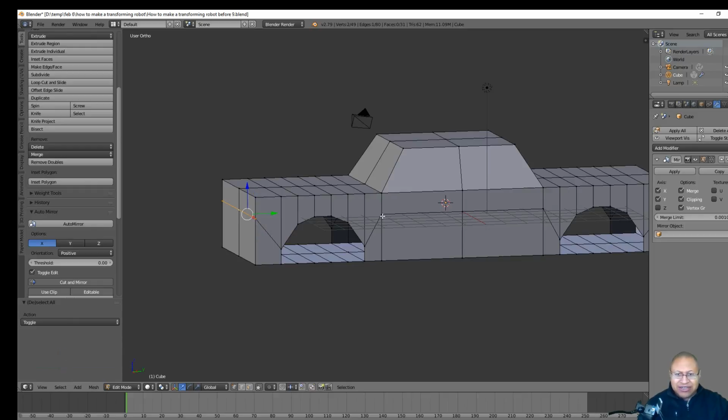We're also going to click here as well as here. So I'm holding shift, and now I'm just going to take the manipulator and push this down. And I just want this to be a fairly straight line in alignment with what's going on with this tire area here. I'm going to press A to deselect.